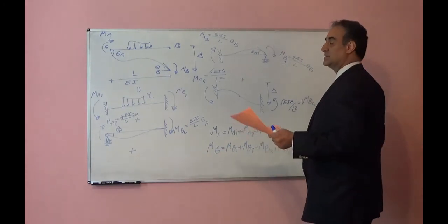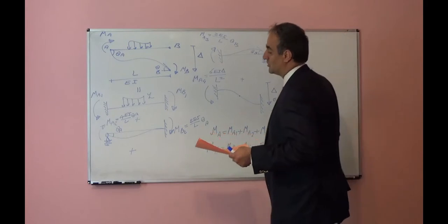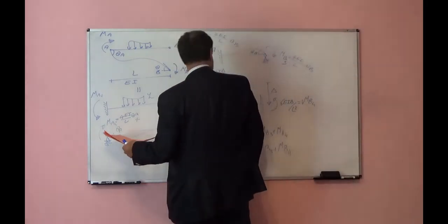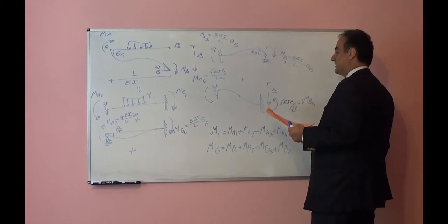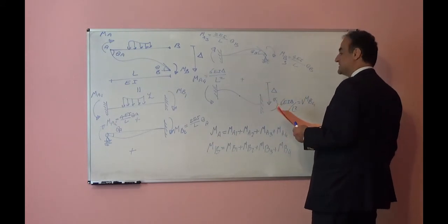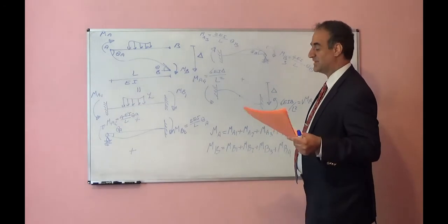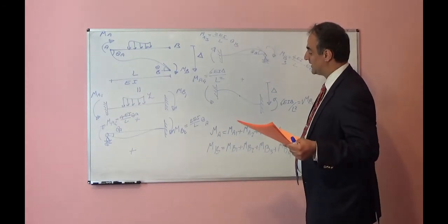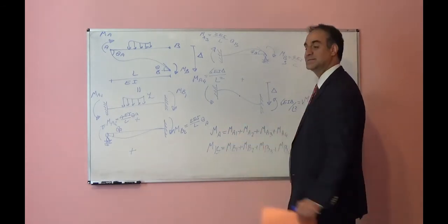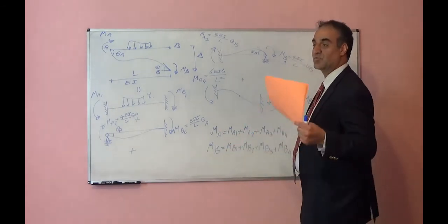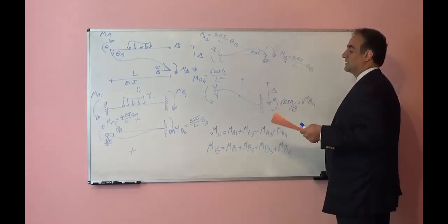Theta is a kind of deformation or displacement. So we have here in terms of theta, here delta is lateral deflection, so it is a kind of displacement. For that reason we call this method the displacement method, because we find the relation between moment and displacement in the form of rotation theta and lateral deflection delta.